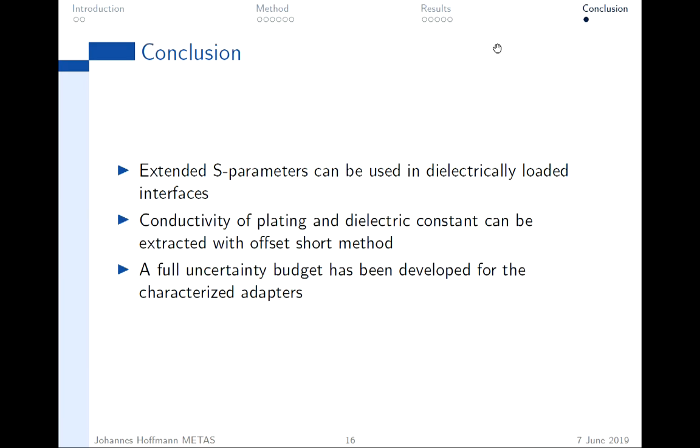Okay. So basically, for the reference plane where I want to know the S parameters, in the center of the connector, what you can do in simulation programs is put an S parameter measurement there, but it will be faulty because the simulator is assuming that you have only one mode propagating there, which is basically not the truth. Oh, I understand.